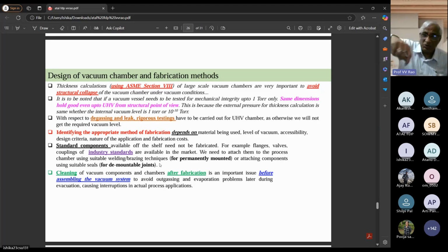For that, you will have to put high vacuum flanges, which are always sealed with metal gaskets. And anyway, it is slowly degassing, so you are never getting into trouble. So better degas it much more before the process is started. That's called degassing. Outgas is when it is coming out naturally. Degas means you intentionally degas it. Outgas is naturally coming, slowly it is coming out. It is so nagging, unless the outgassing is completed, you cannot start your process.